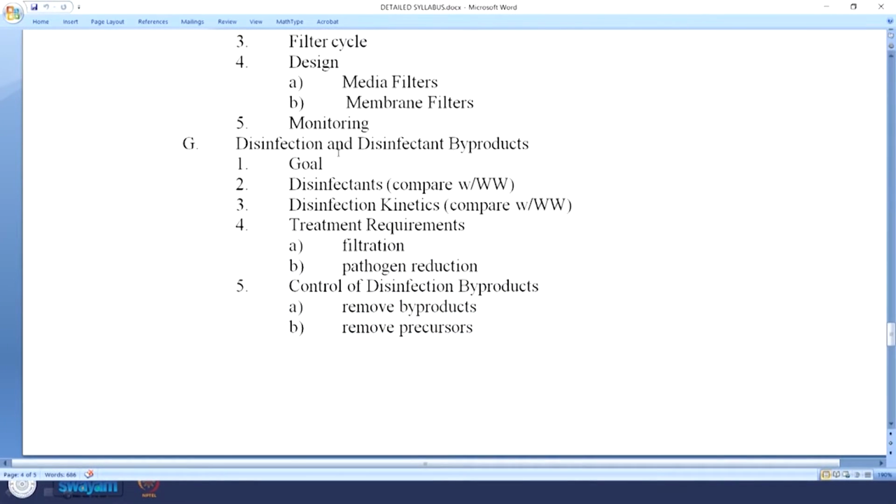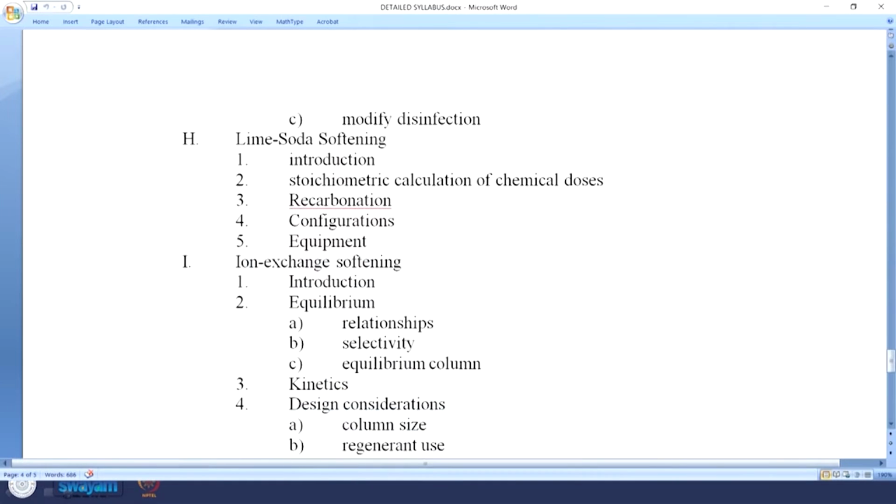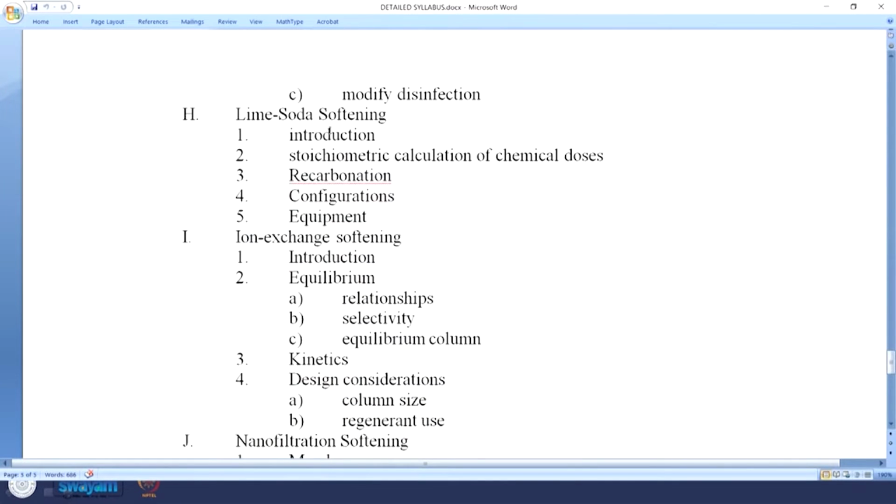And then disinfection by chlorine or HOCl, and the issues with such disinfectants, I guess that is something you are going to look at. So, softening, because if you remember, we looked at the data from the village near Roorkee and we saw that the hardness was pretty high. Other than leading to issues with your digestive system, it will typically lead to issues whenever you are trying to wash something, because it is going to use up or form a complex, if I may say so, with your soap, let us say, right.